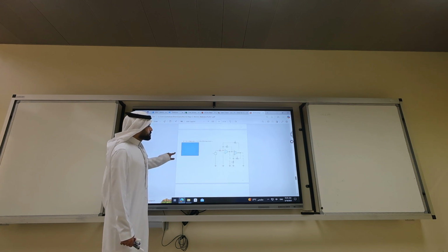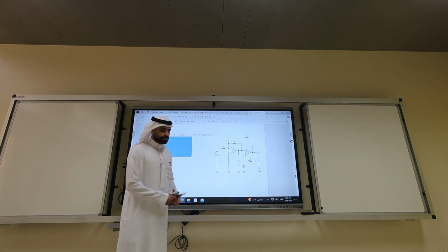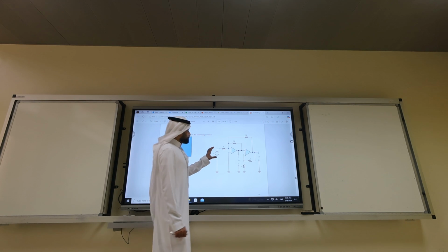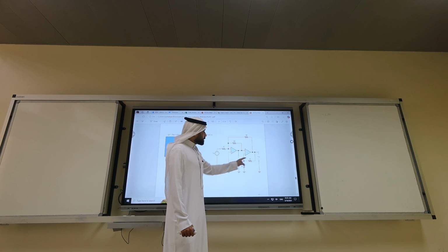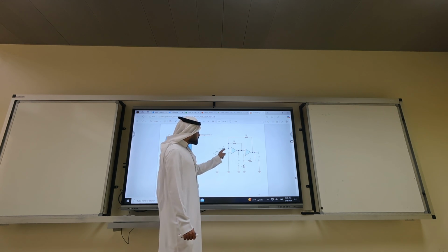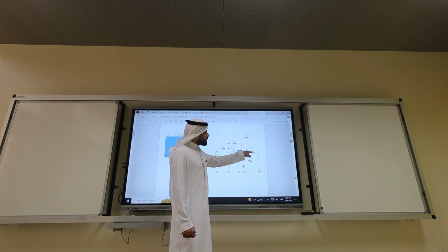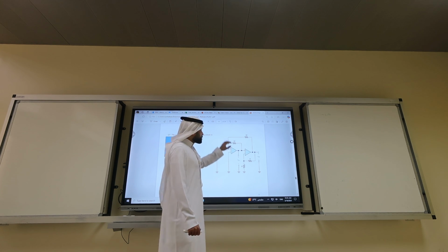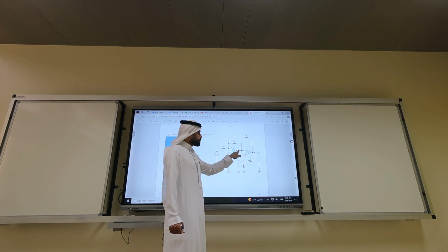So let's do some review about chapter 13. We have two op-amps, okay? The first one on the left, it is inverting, but there is a trick. We also have a negative feedback from the second stage output. So if you remove this resistor, the gain will be easy. Minus 2R over R times V input here.